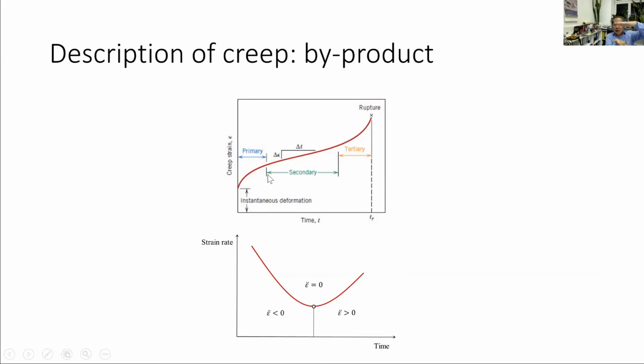You first load the sample with a constant strain rate, and at some point I want to start a creep test, which means the load is kept constant. In order to get there, you first need to decelerate. You see here, decelerate, and finally we come to acceleration equals 0, which is basically our secondary stage.